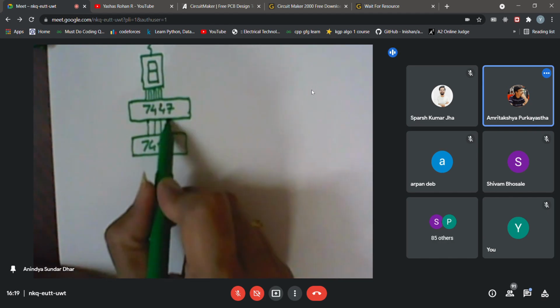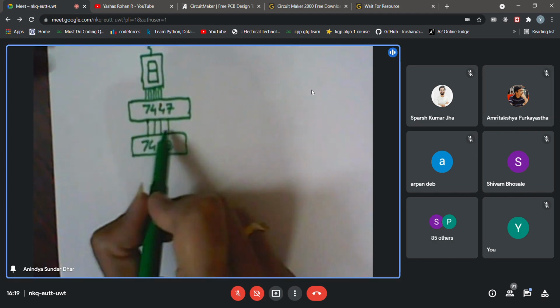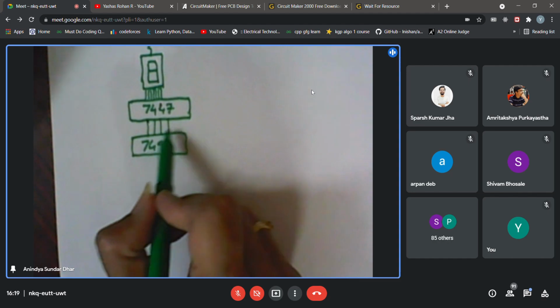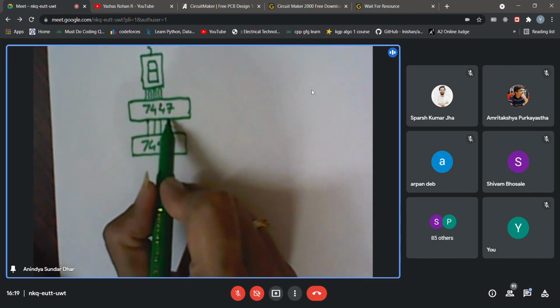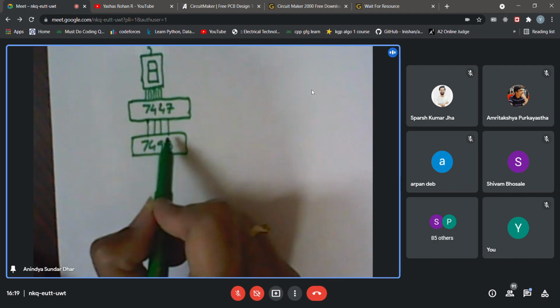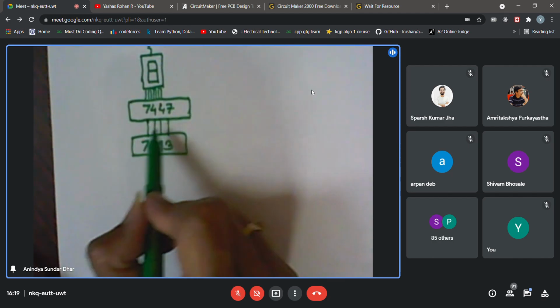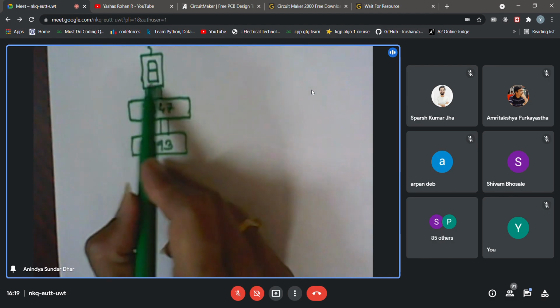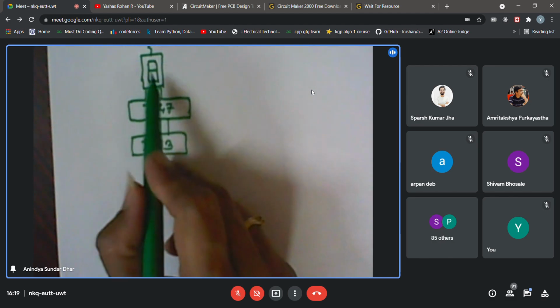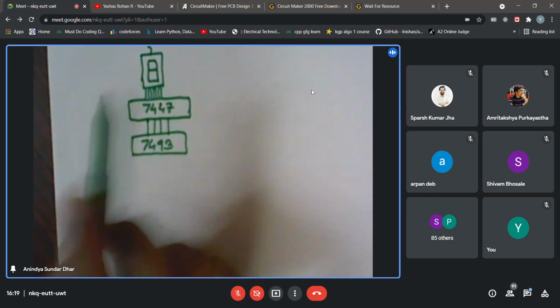4. Right. So while connecting these 4 connections, maybe you have mixed up the connections. That LSB of 7493 is not going to the so-called LSB of 7447. You have mixed it up. Either you have completely cross-connected that, say LSB goes to MSB and so on, or it might be a permutation of that. So you are not getting the proper sequence of 0, 1, 2, 3, but you are getting something else. So what is the easiest way to debug this?